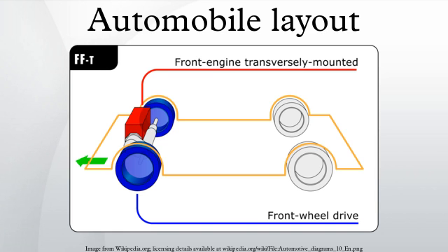However, powerful cars rarely use the FF layout because weight transference under acceleration reduces the weight on the front wheels and reduces their traction, limiting the torque which can be utilized. Electronic traction control can avoid wheel spin but largely negates the benefit of extra torque power. A transverse engine is commonly used in FF designs, in contrast to FR which uses a longitudinal engine.